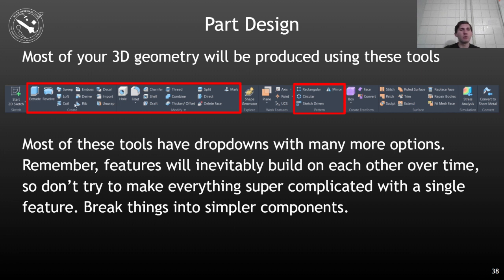There's a handful of other ones that I won't really go into. There's also holes. You can pick a point and pick some standard hole size, like a metric 3 millimeter hole. It can be a clearance hole or a tapped hole, meaning it has all the threads on the inside. A clearance hole is just something the screw passes through without engaging with it. It can just slide in and out. You can pick a bunch of different sizes based on standard dimensions.